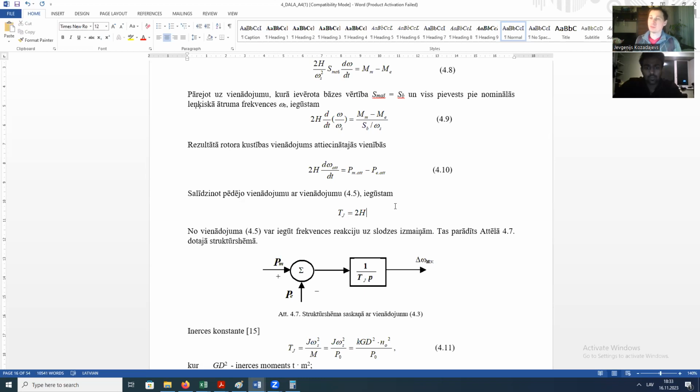But when will we see this deficit in the power system? The main parameter that shows the balance is frequency, as we discussed. If frequency is up, we have too much generation. If frequency is down, we don't have enough generation because we have a big consumption. So in this case, if we are controlling or analyzing a power system, if we're modeling regimes for